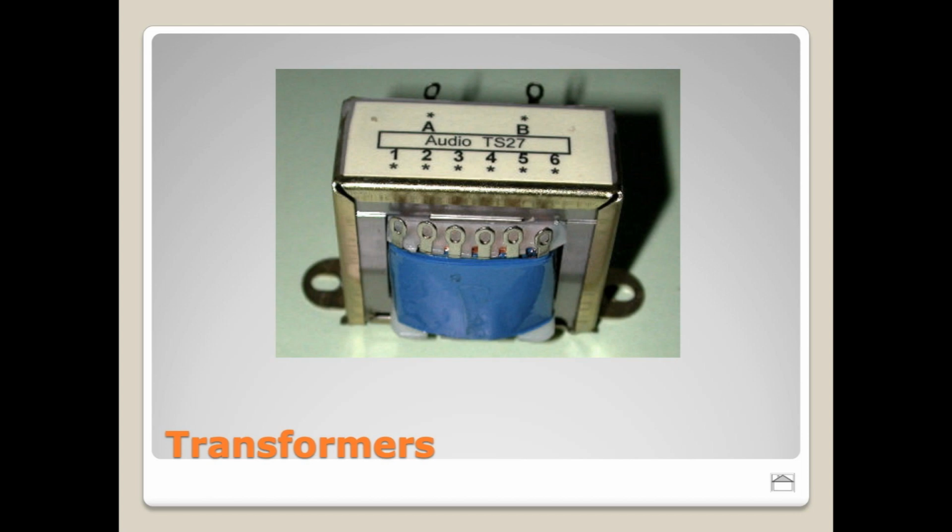So if you are opening up a piece of equipment that has a bad transformer and you're trying to find a replacement for it, you should be able to find, again, a schematic that has some of that information. Or you can look at the owner's manual. You can call somebody who's done some service on these before and knows a little bit more about it.